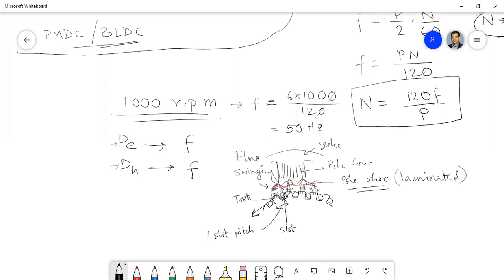So that means there is a spatial distribution of flux density in the pole shoe. If this spatial distribution were fixed, then there would be no question. But this spatial distribution is also not fixed in time, because with the armature rotation it also changes. Therefore the magnetic flux reversal will come, and that frequency is not the frequency of the magnetic flux reversal in the armature core. That is a much higher frequency.